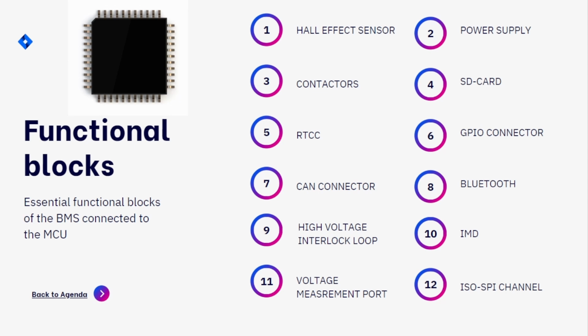The contactor selection is mainly based on the charge and discharge current. We can go for a MOSFET based solution for a low current and low voltage application instead of the contactor.